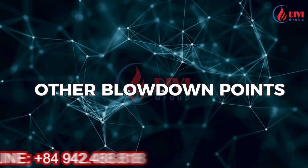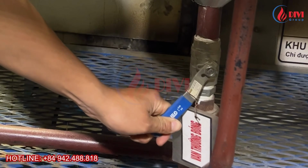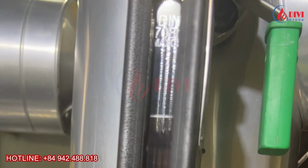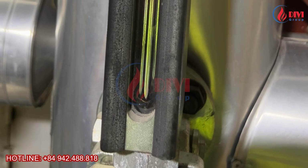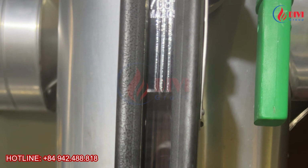Other blowdown points, for reflex gauge glass, transparent gauge glass, and surface blowdown, only require simple valve opening and closing. There is no need for burst operation like in bottom or furnace blowdown.